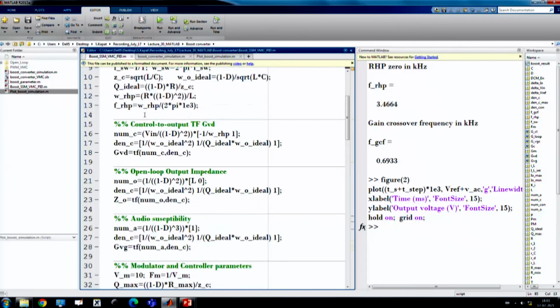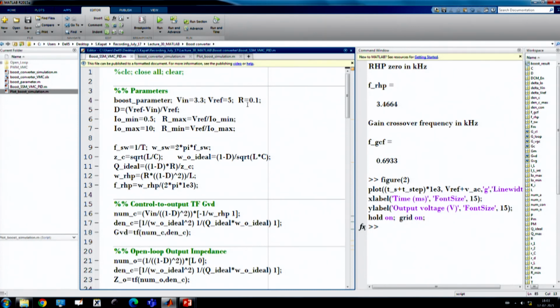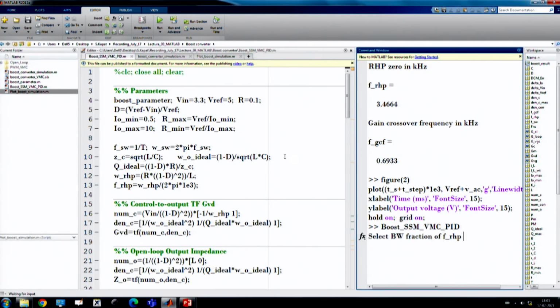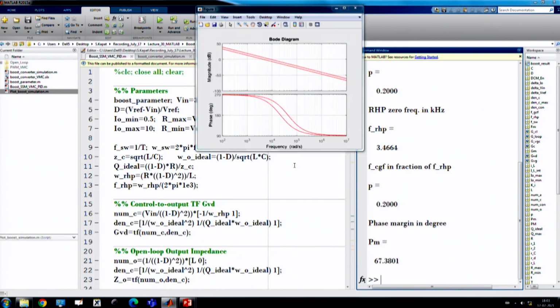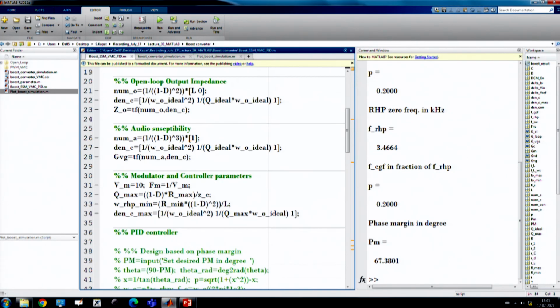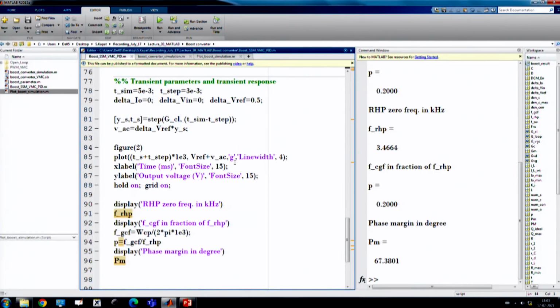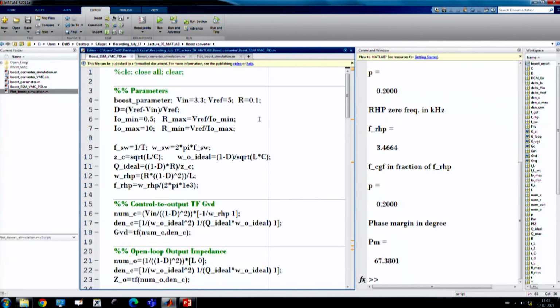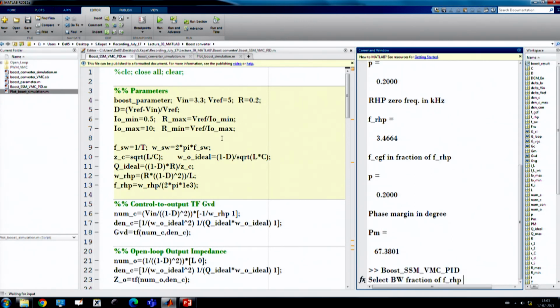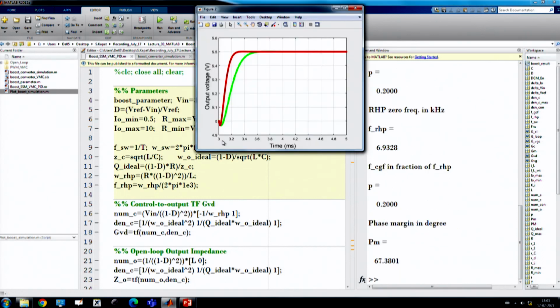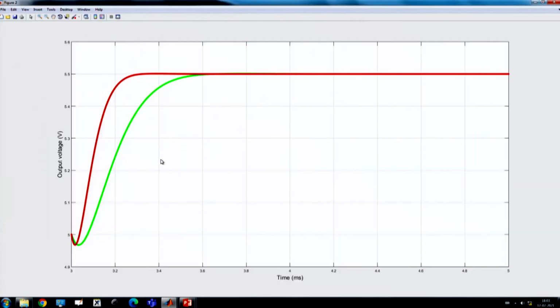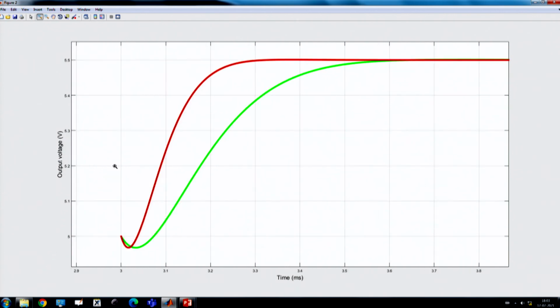That means, this is the case 1/5, and if we hold this same value with the red color, and if we change the load resistance to 0.2 and if we do 1/5. So, I want to show that because in the second case the right half plane 0 is coming close to the imaginary axis, the bandwidth of the controller is smaller.